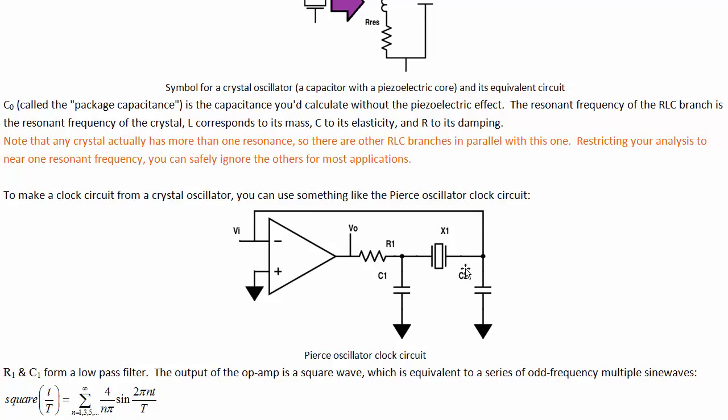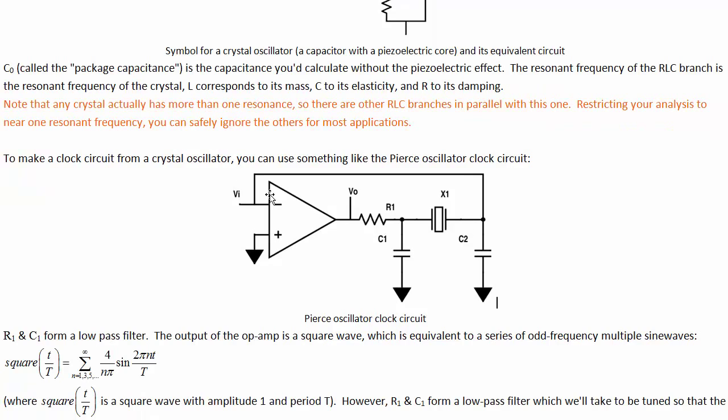So here's how this works. The op amp, we're hooked up to the inverting terminal, so we're going to get an output here, which is proportional to the negative of the voltage here, except because we don't actually have the right sort of circuits for feedback, this is just pinned to 0. Whatever voltage here is, if we've got a positive voltage here, then this op amp's behaving more like a comparator, and so we're going to be pinned to negative Vs. If we've got a negative voltage here, we're going to be pinned to positive Vs.